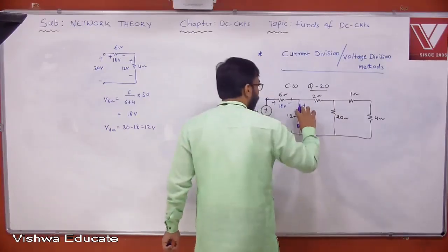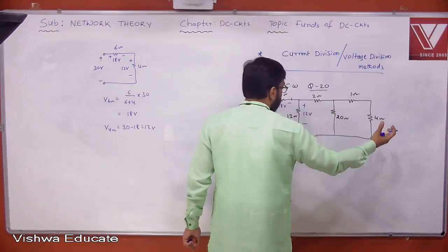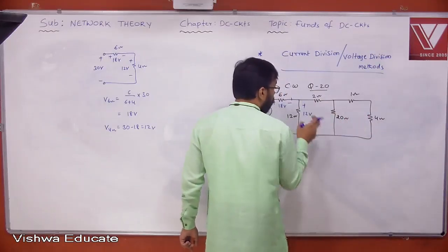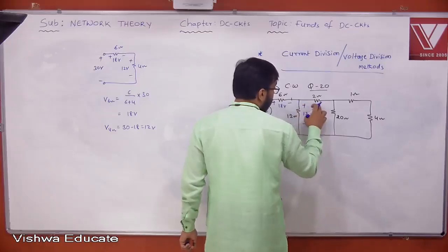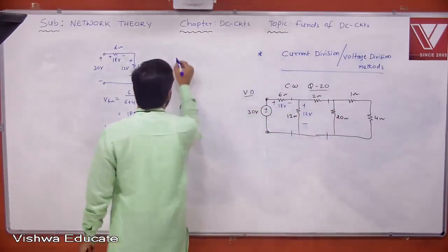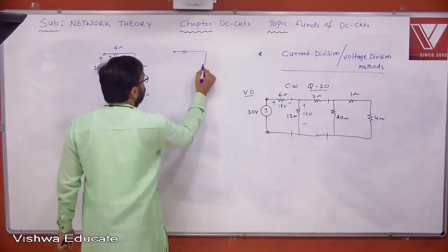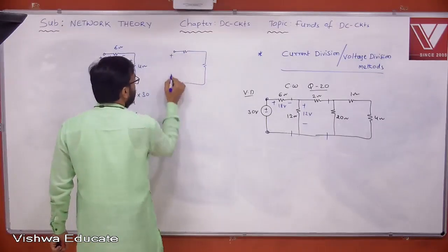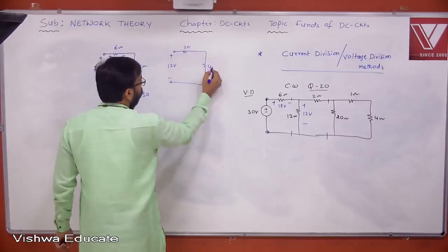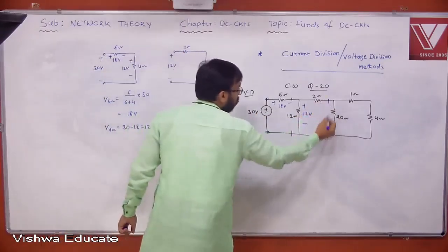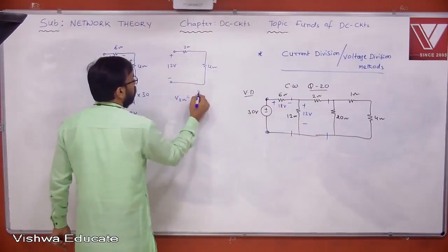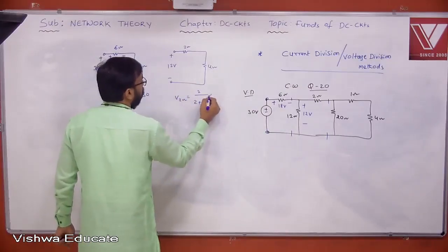Now, these 12 volts are supposed to be divided again further. But for that you require two series elements. One series element is readily available here, but for another series element, you need to reduce the network temporarily once again here. I'm just going to reduce the network, something like this. Now plus minus 12, okay, this is what, 2 ohm. Again you got 4 ohm, okay, up to these 2 points you got 4 ohm, you see. Now voltage across 2 ohm is 2 by 2 plus 4 into 12.